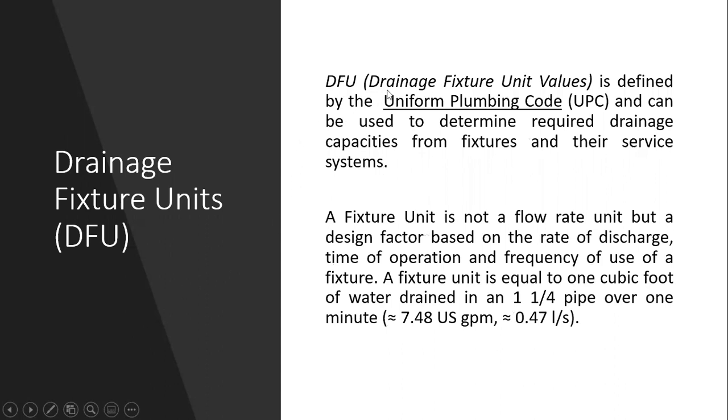The DFU drainage fixture unit values is defined by the Uniform Plumbing Code UPC and can be used to determine required drainage capacities from fixtures and their service systems. A fixture unit is not a flow rate unit but a design factor based on the rate of discharge, time of operation, and frequency of use of a fixture.